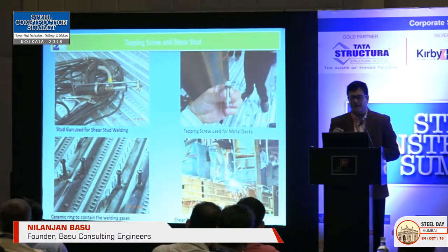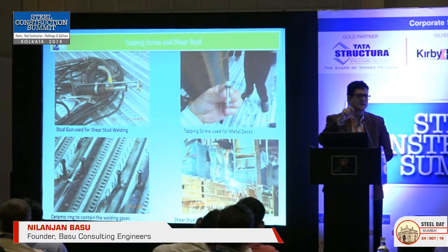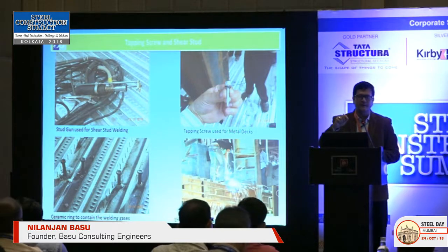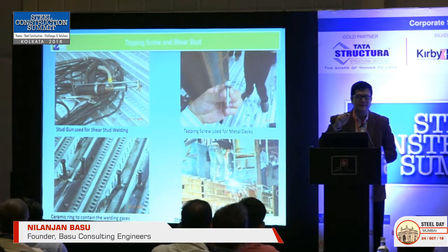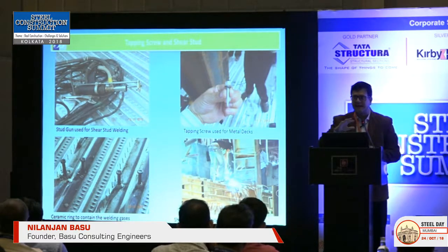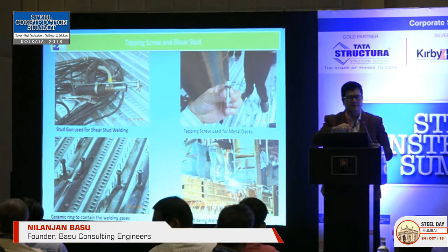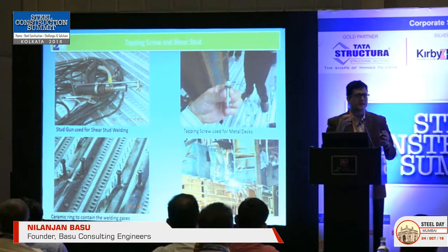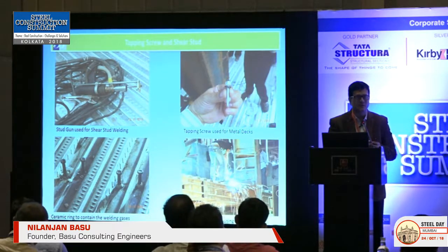For the decking, before the shear stud is put in or welded into the deck, we have to make sure the deck is in place. And for that, we use a tapping screw. That tapping screw is not to be screwed in with just a screwdriver or any local made material. It has to be done with a tapping gun because it has to penetrate the flange of the beam effectively without disturbing the deck.